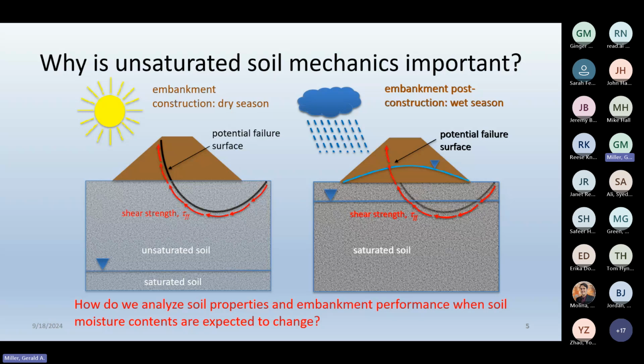Yeah. And the behavior is significantly different because, as you know, water is incompressible. And so a lot of our fundamental soil mechanics that we learned as youngsters was based on saturated soil principles. But when you introduce air, it's a highly compressible fluid, and that changes the behavior along with the interaction of the air and the water. That leads to what we call capillary pressure. And we're going to get into this more and more.